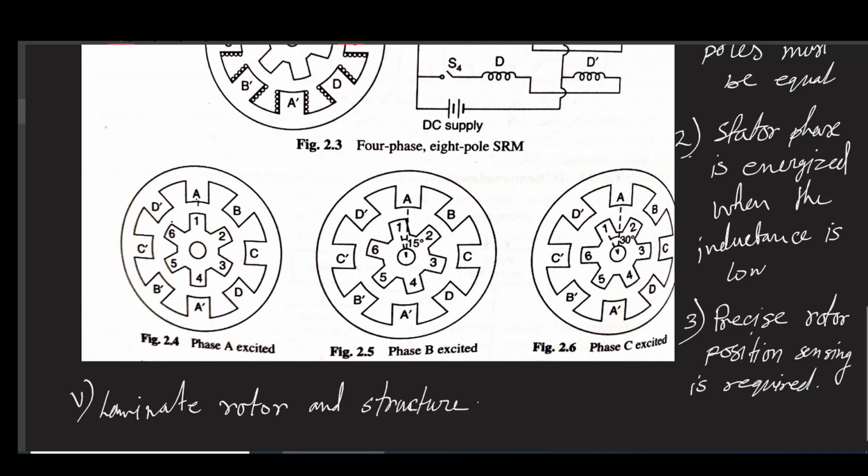ventilation, or make your cooling of the machine very easy, because as I said, all these are very small machines of very compact shape and size. So here we don't have what we rate for large scale machines, some of which have air cooling, hydrogen cooling, forced cooling. All this engineering you cannot do here, which is possible on a larger scale. This is not possible when the volume and weight of the system matter. So here we must be very cautious to cut down all the unnecessary sources of heat generation.